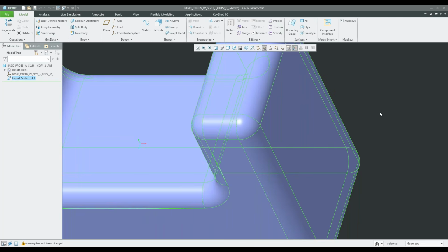So if I want to make an edit to the newly created surface and any part of the original surface, I can't create that edit correctly unless it's part of the original fold of surfaces, and it actually merges them together. Kind of like when you're in Creo and you have an original surface, if you create a new one, you use the merge feature to merge those two together. So it also works in a sense like that as well.